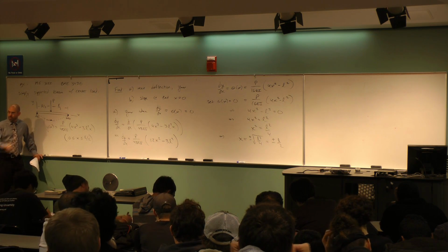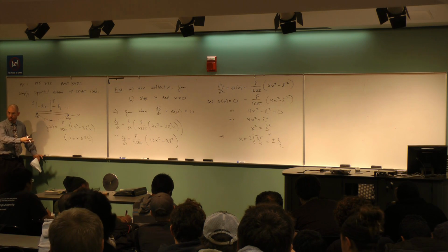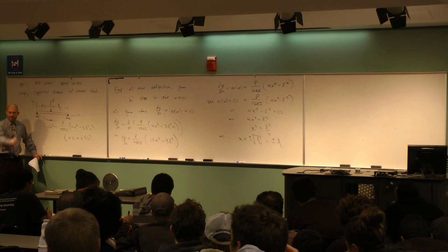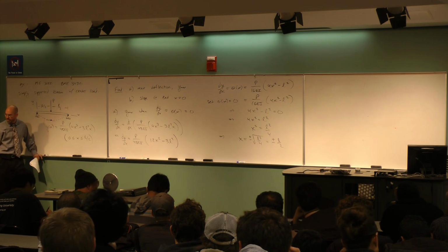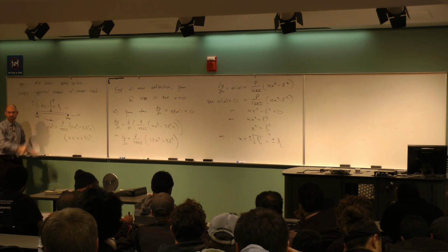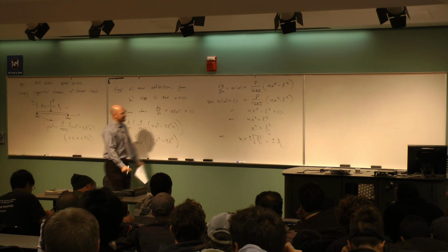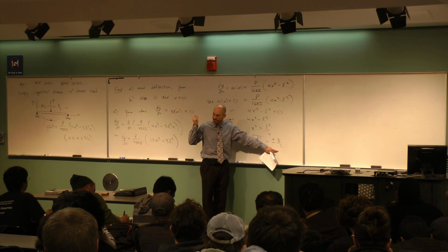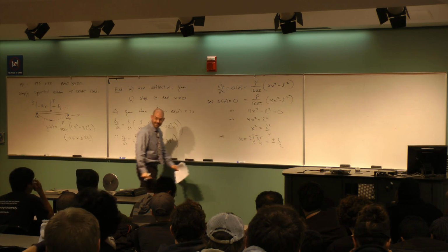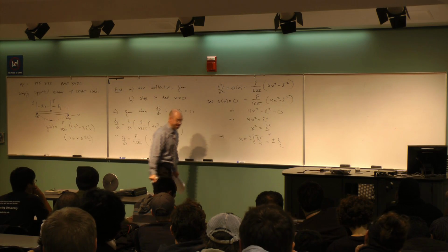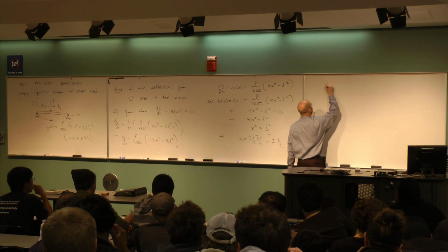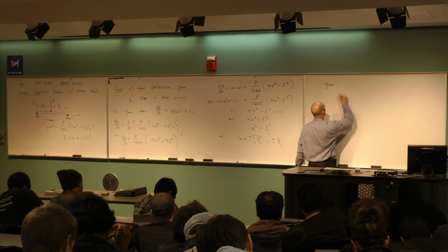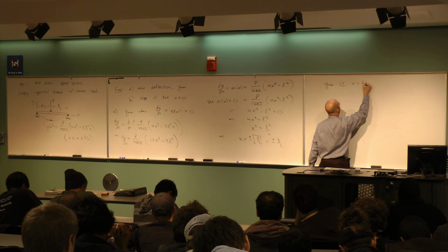In general, when I have a physical problem and I represent it with an equation, my physical problem has a physical domain. The math might exist outside of that physical domain, right? You've got to limit your attention to where I actually have a beam. Just because there's two answers to this math doesn't mean there's two answers to this beam. There's only one answer to this beam because minus L over 2 is not on the beam. Okay, and so this means that Y max occurs at x equals L over 2.